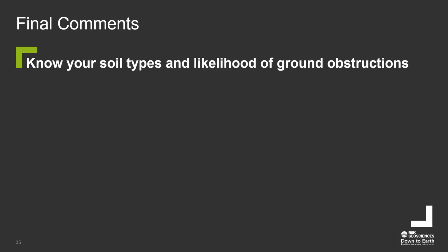Final comments from me. Ultimately, you need to know your soil type. If you've got a clay, then you load it. The water in the void space of clay will not move quickly, and therefore you have to know that. And if it's a poor quality soil, it will reduce in its void space and it will settle. And it's trying to predict how long that will take.